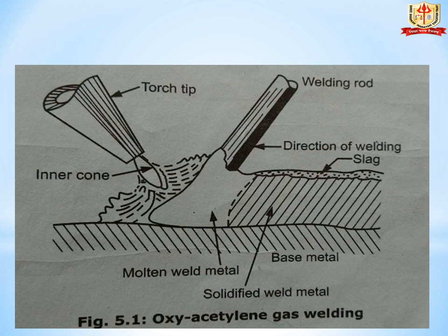A pressure regulator is fitted on the cylinder for adjusting the working pressure of welding. In general, the working pressure of oxygen required for welding and cutting is 0.35 and 3.5 bar respectively.